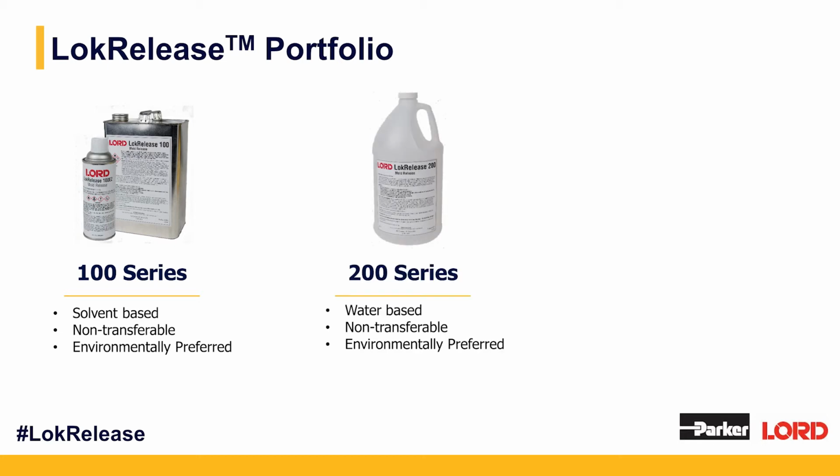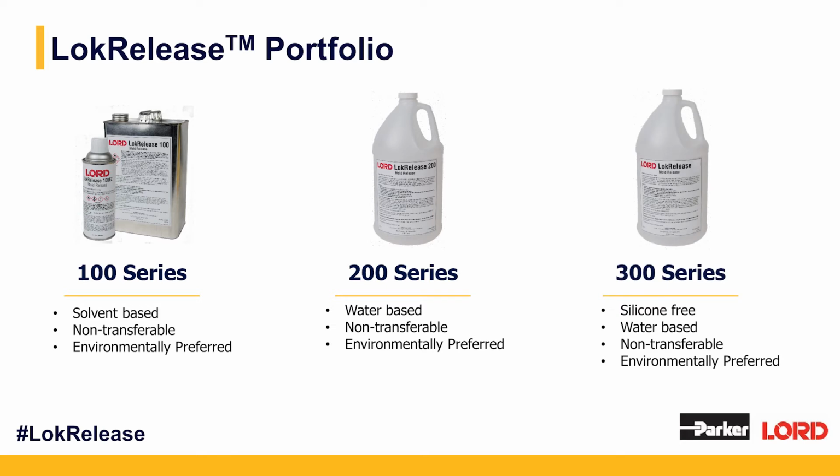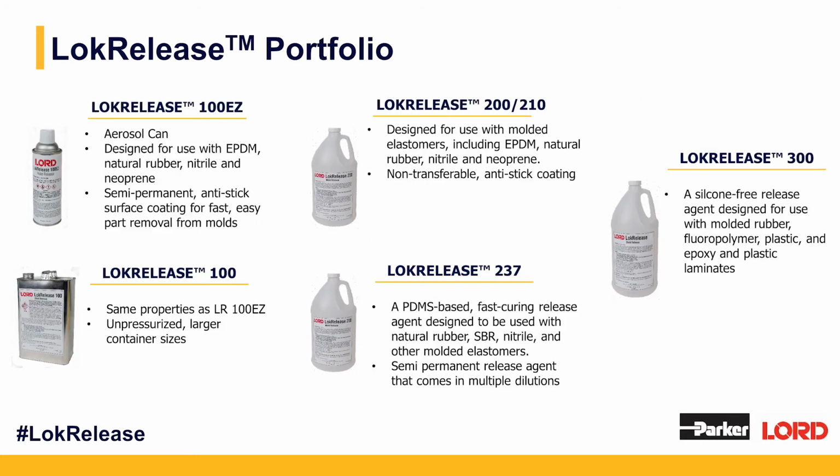The 200 series products are water-based mold releases, making them environmentally preferred as well. They adhere well to the mold, providing a strong, non-transferable release agent. Our 300 series is also a water-based mold release, providing a silicone-free product option. Like the other series, these are non-transferable to the rubber surface and environmentally preferred.